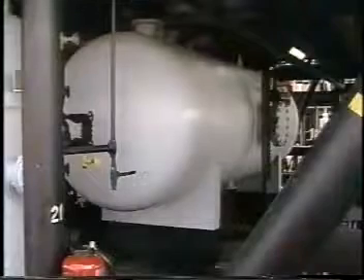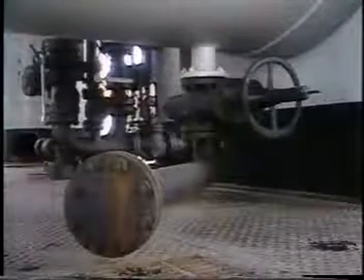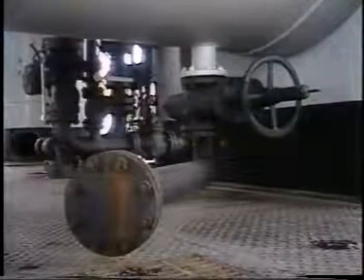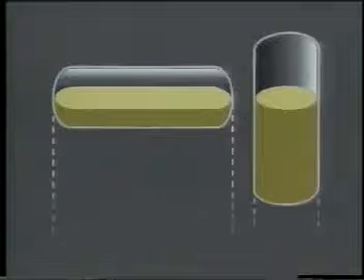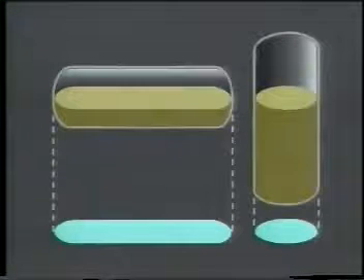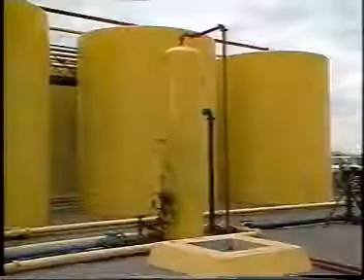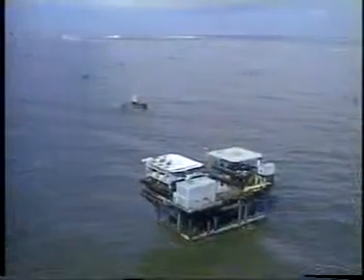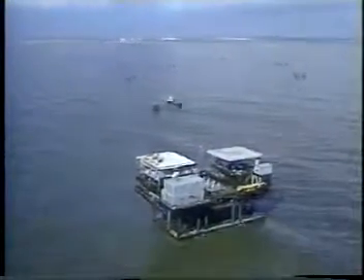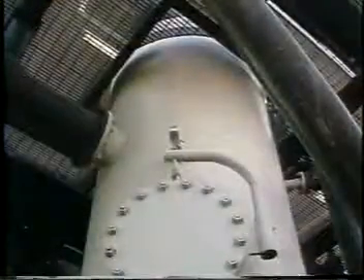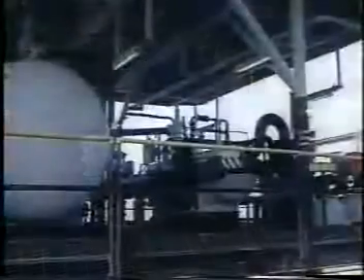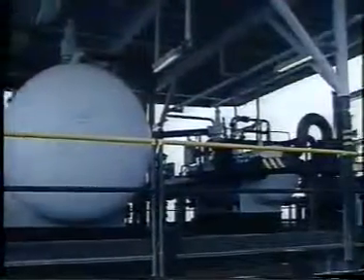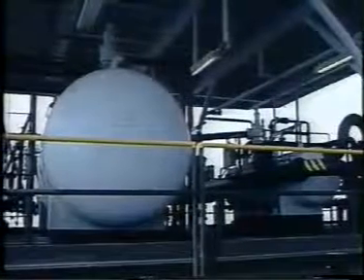In a horizontal vessel, it is necessary to place several drains along the length of the vessel, spaced at very close intervals. Horizontal vessels also require more plane area than a vertical vessel with the same capacity. While this may not be of importance at a land location, it could be very important on offshore production platforms where space is at a premium. On the other hand, horizontal vessels may fit more easily in cramped lower decks and underneath heliports.